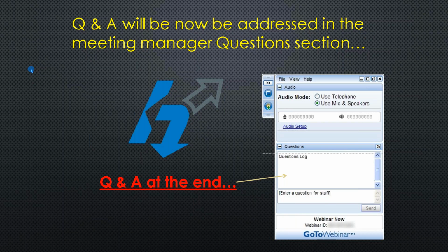At the same time, I could also go so super fine that I could start to see stresses in areas that really shouldn't have stress. And that's typically something you're going to see pretty quick. You're going to notice that. But if your mesh is too coarse, your numbers are off the same way. So you want to find that sweet spot.